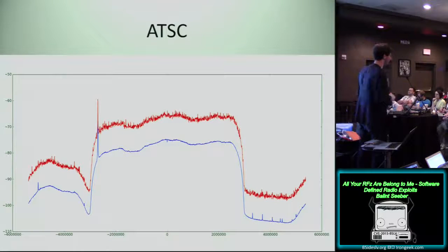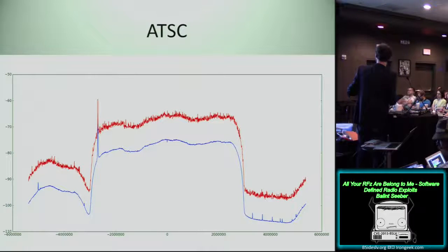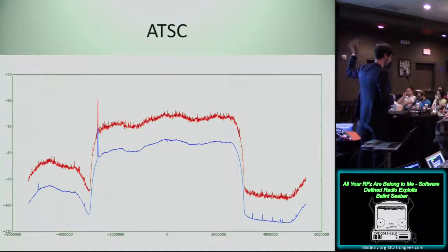So, I thought it would be interesting to try to visualize multipath using a really common signal that's out there. And this one I chose as ATSC, the digital television standard for North America. Like you saw in the spectrum monitoring code earlier in the talk, here I'm using that same code to capture some TV signals for a period of time.